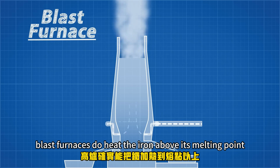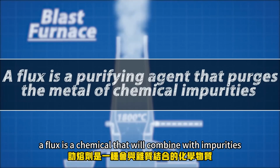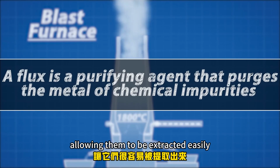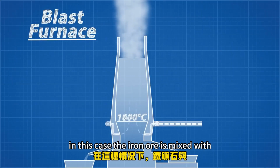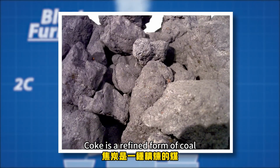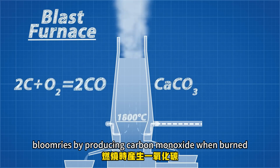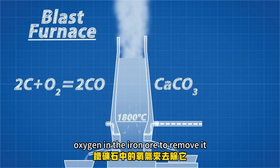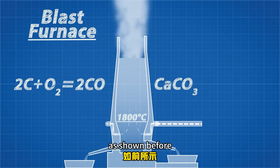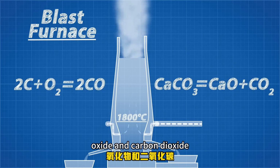Blast furnaces do heat the iron above its melting point, along with flux materials. A flux is a chemical that will combine with the impurities, allowing them to be extracted easily. In this case, the iron ore is mixed with limestone and coke. Coke is a refined form of coal, with very little impurities, and it works similar to the charcoal in the bloomeries by producing carbon monoxide when burned, which in turn reacts with the oxygen in the iron ore to remove it, as shown before. The heat from the process decomposes the limestone into calcium oxide and carbon dioxide.